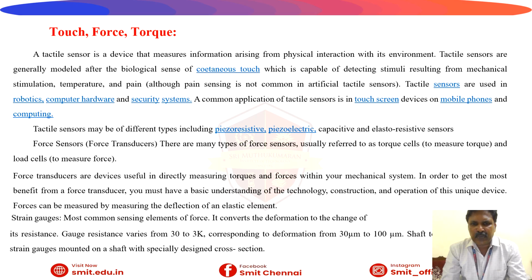Tactile sensors may be of different types, including piezoelectric, capacitive, and resistive sensors. Force sensors, that is force transducers. There are many types of force sensors, usually referred to as torque cells to measure torque and load cells to measure force. Force transducers are devices useful in directly measuring torques and forces within your mechanical system. In order to get the most benefit from a force transducer, you must have a basic understanding of the technology, construction and operation of this unique device.